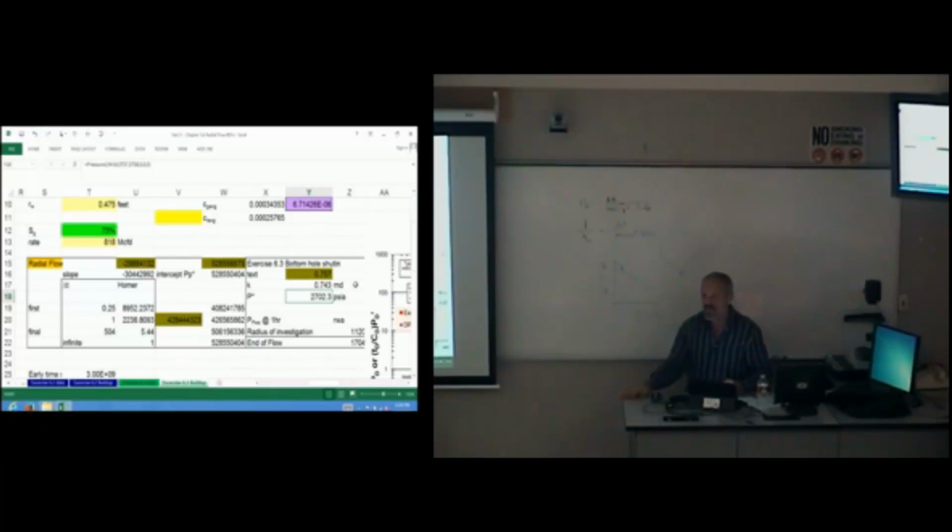Maybe it's things like phase angle, the way they perforate, the number of shots, perforations per foot, or oftentimes there's a problem with depth corrections, and they perf the wrong thing. If you've got stringers and you're off a little bit, and you don't get enough perfs in the actual pay zone, it'll show up as a large skin.